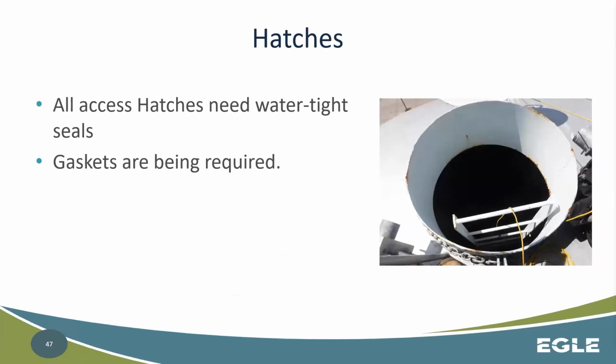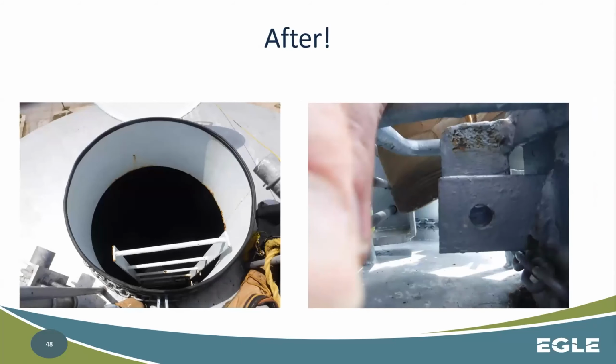All right, so you also have hatches on all of your storage tanks. The biggest thing that this slide specifically is talking about is that this should have a gasket here. Again, trying to maintain sanitary conditions while also making it a workable piece of equipment, right? So that would be just steel on steel. That is not ideal. Things can get in there. You can have whatever bugs getting in there and having bacteriological issues that you won't know until you get up there and realize, oh, there's a hole here and there's bugs, or something, debris, whatever the circumstances are. So this is fixing that.